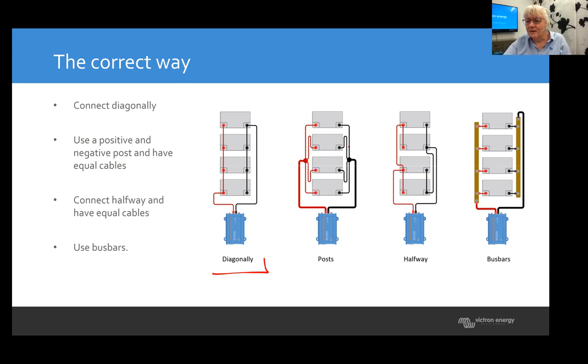So that means that in these systems you have longer wires. My preferred way is a nice long bus bar, and you put all the batteries in between. It can even be a shorter bus bar, but again, same path. And if you connect the bus bars, same thing: go diagonally on your bus bars like that. So that's important. If it's a really big system, you intermix inverters and batteries and all sorts of other things on the bar. But yeah, that's all in my book.